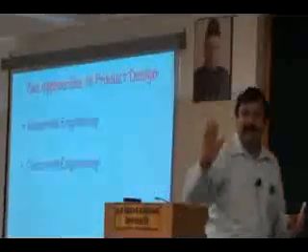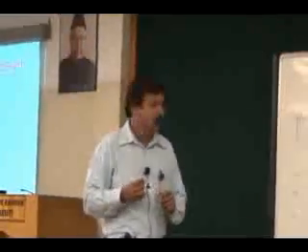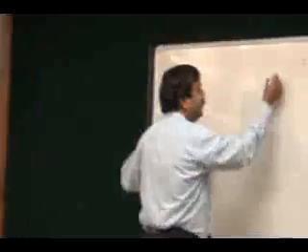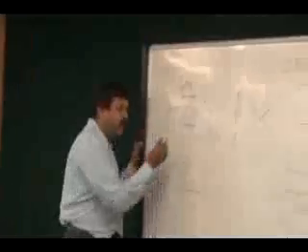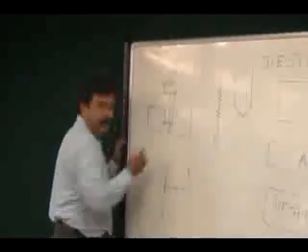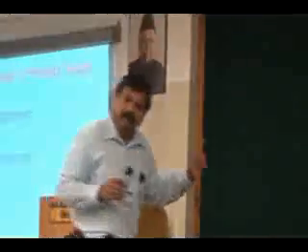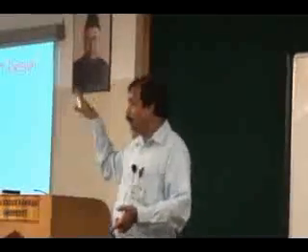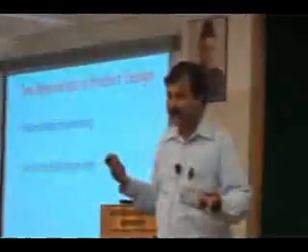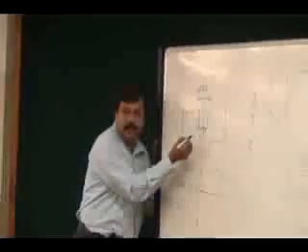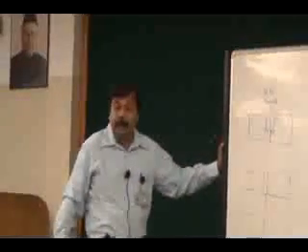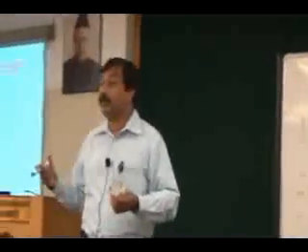When I make a hole with a drill, the drill bit will look something like this. It can only make a hole like this, or it has to be a through hole. When I make a through hole, that is not an issue. Now, making such a small change in the drawing makes a lot of difference for the manufacturing engineer.